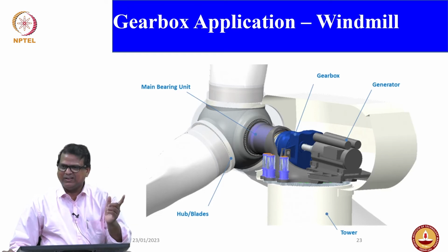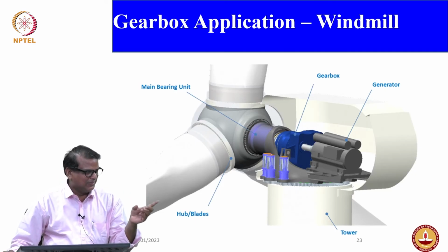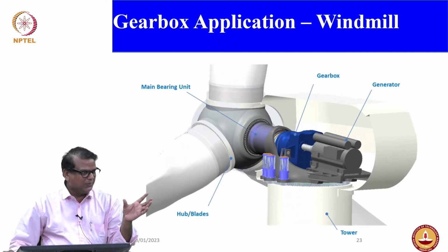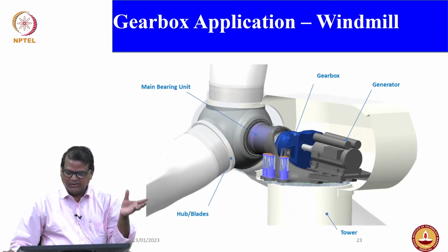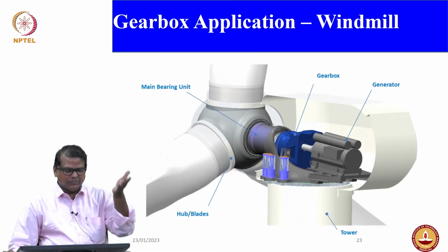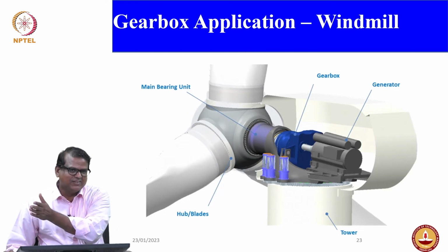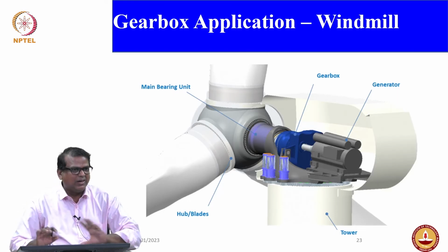The more the speed, the more the electricity. So both are very different applications, right, you can understand that. In a windmill you will usually have an epicyclic gear train in the first stage, then a regular 2-stage helical gearbox, such that you can have a high speed. So the dynamics are different.